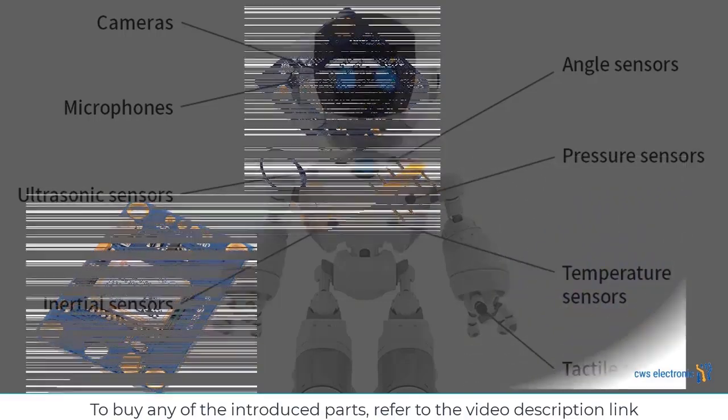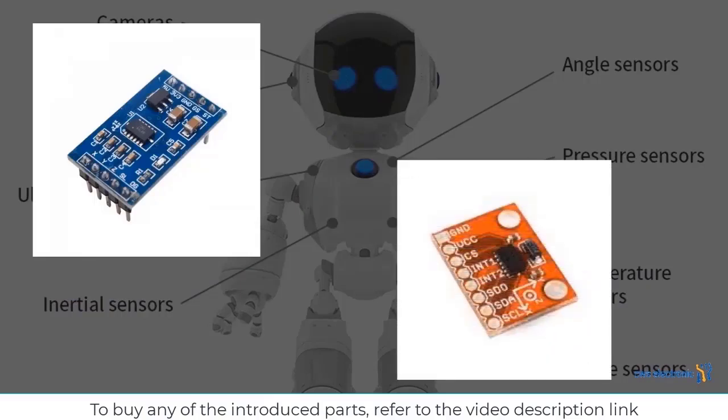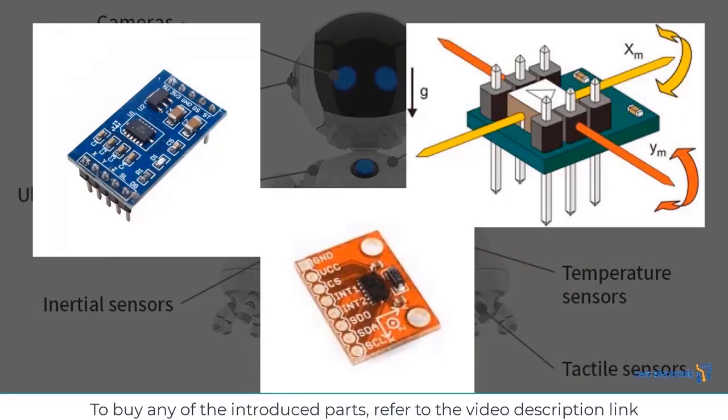The next sensor is the accelerometer sensor, which many people confuse with a gyroscope. Maybe there is no need to explain much about it, but I will explain it to you. It is better to know that the accelerometer sensor is used to measure the amount of motion and acceleration. What you need to know is that to calculate acceleration, we need to calculate two forces. One is a static force, and the other is a dynamic force. For example, the gravitational force of the Earth, or gravity, is a static force that acts on an object, which is also an object for a robot.